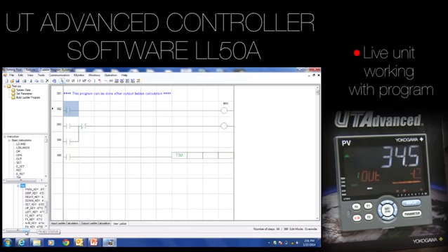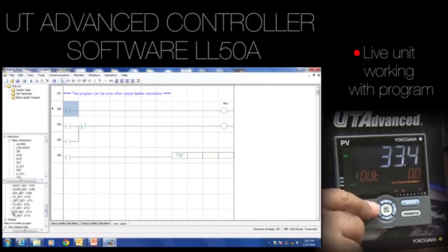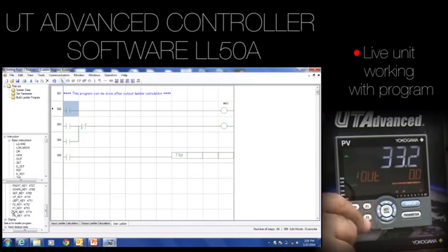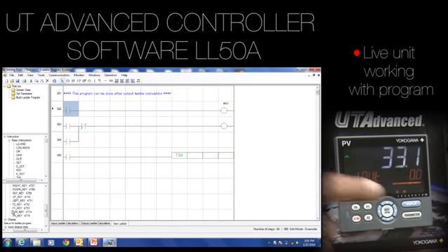All right, let's take a key function here. Let's assume we're going to start this process by using the F1 key. The F1 key is here, and we're going to use that F1 key. I don't know what it's doing. It doesn't look like it's programmed for anything, but we're going to program it to start this basic process. So we're going to take this F1 key status and drag it up here. That's going to start the process. M01 is going to come on when that starts.